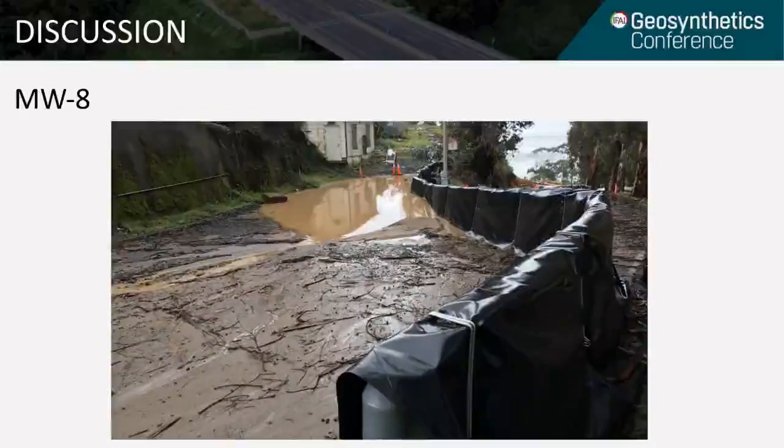While basin MW8 was placed on asphalt, contained empty barrier walls, and also utilized those 90-degree corner wall pieces, it didn't experience any stability issues. And this is likely because the basin was located on a 5% slope as compared to that 10% or greater threshold we were discussing earlier. And the basin also never filled to capacity due to its upslope location on the hillside.